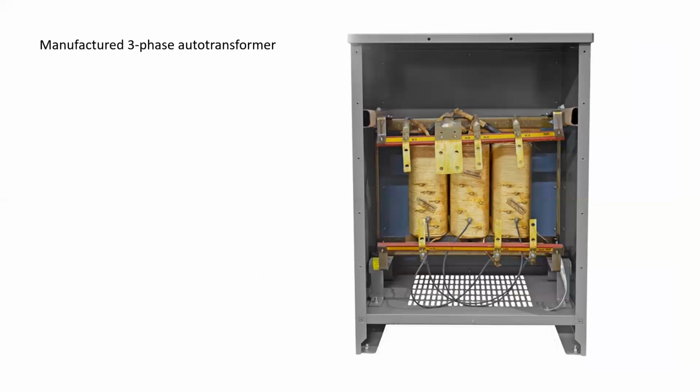On the actual connections, again, we really don't have much difference when it comes to the actual terminations. We're going to have X terminals and H terminals. And other than the weight of the unit, we really won't be able to tell that this was an auto transformer versus an isolation type transformer. Instead of having a high and a low voltage winding here for A, B, and C, there's actually only a single winding. One single winding here, a single winding for B, and a single winding for A, hence the non-isolation or auto transformer.